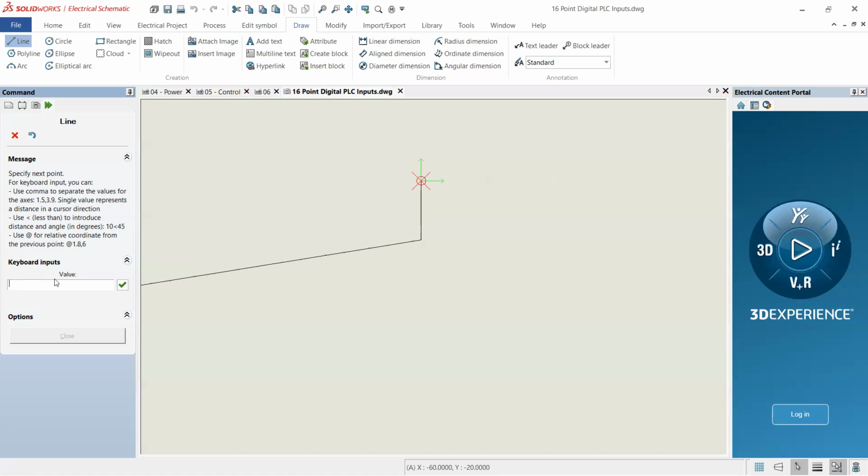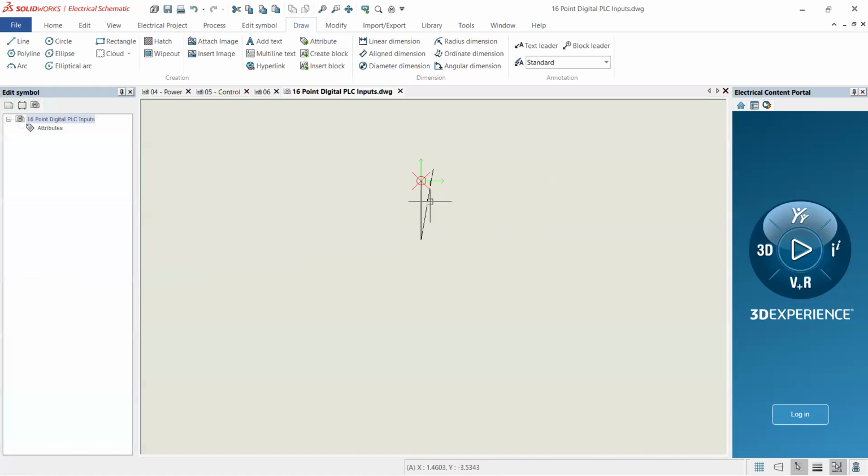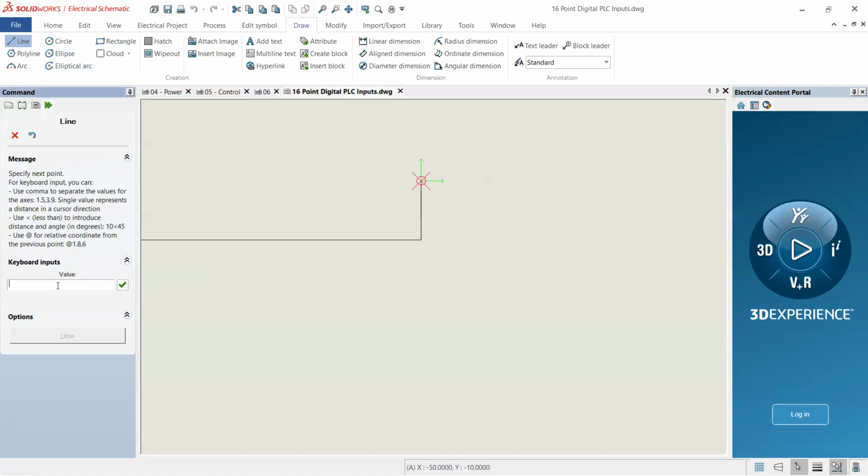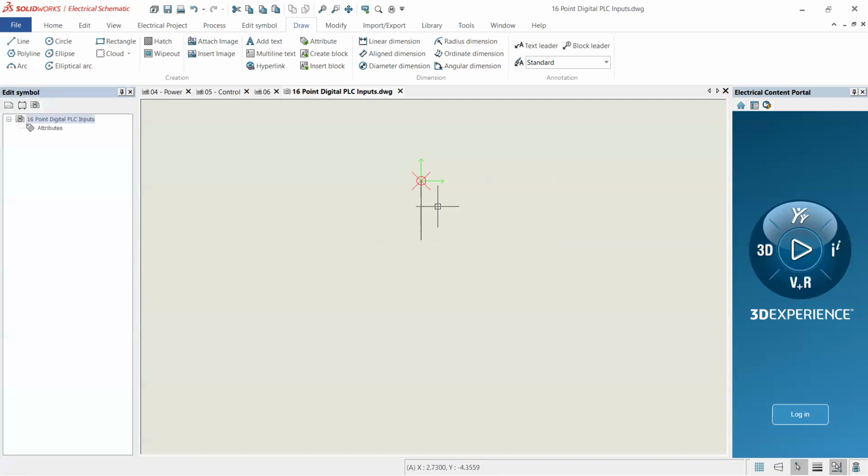So for instance, if I just typed in, let's say 2, comma 2, just so we have something in there, right? That's the line it just created. Okay. Let me delete that. If I use relative coordinates that start with an at 2, comma 2, instead of going to 2, 2, it's going to move 2, 2 from where it is. So at 2, 2, notice that's a way different line than what I just got. So at our relative coordinates, that is important to remember.